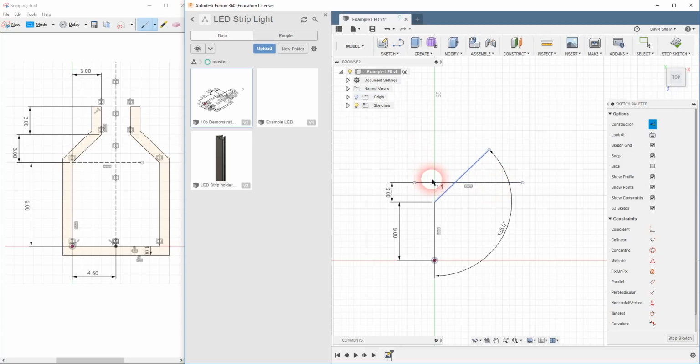Okay, so I'm not very happy with the fact that that entire line is kind of highlighted there with a dimension line. That seems a bit strange. Can you see how that kind of highlights the whole thing? So if I delete that and get rid of it, can I actually define it like there? Okay, let's just try that again. D for dimension line from that point to that point. I'm preferring that. That was much better. So I actually went from point to point rather than the whole line to this point. And now I can see that's an actual construction line because it's dotted.